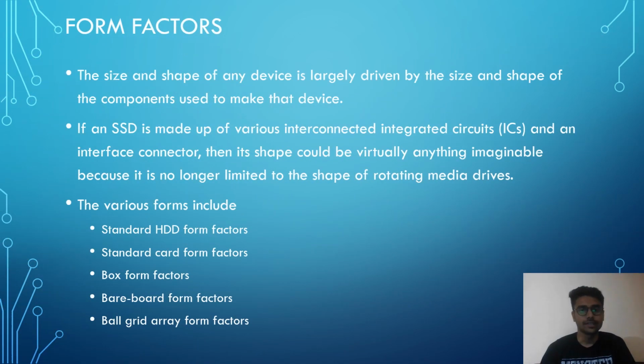Form factors. The size and shape of any device is largely driven by the size and shape of the components used to make that device. If an SSD is made up of various interconnected ICs and an interface connector, then its shape could be virtually anything imaginable because it is no longer limited to the shape of rotating media drives. The various forms include standard HDD form factors, standard card form factors, box form factors, bare board form factors, and ball grid array form factors.